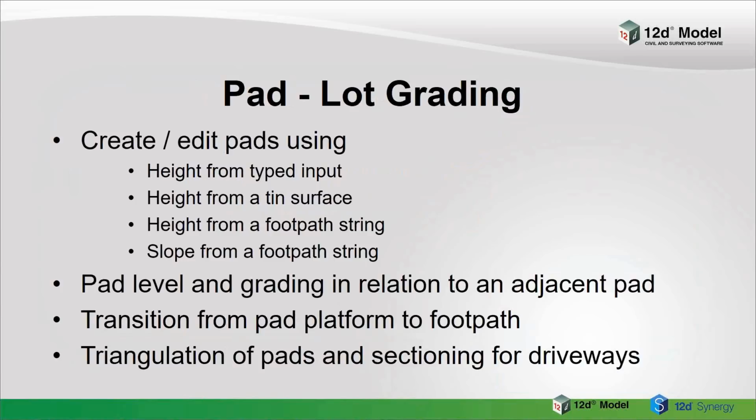So the pad leveling and grading in relation to an adjacent pad is fairly important when you're trying to set up each pad for heights of retaining walls and different sorts of earthworks. So we're going to also transition the pad from the pad platform to the footpath. Rather than just having a pad sitting up in the air, we need to do that transition.